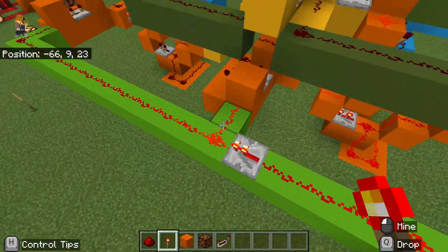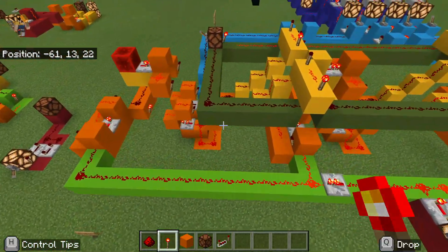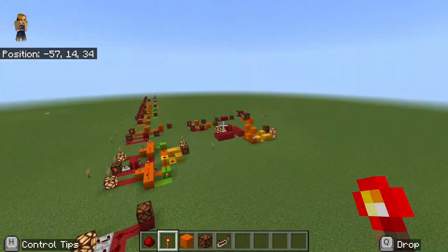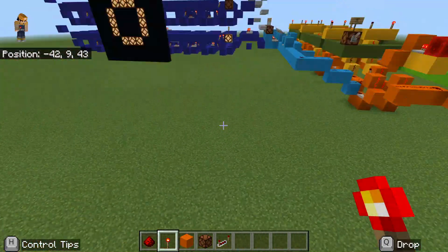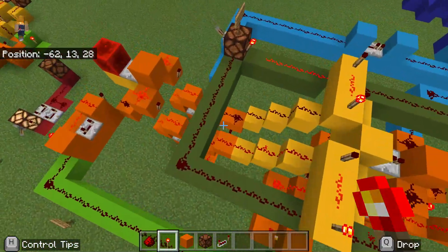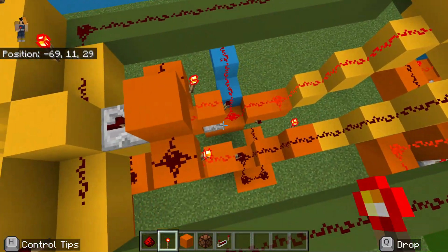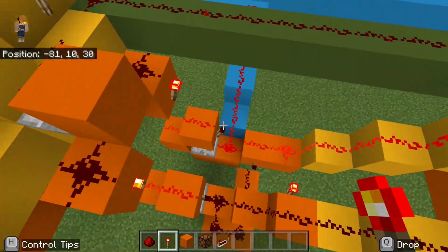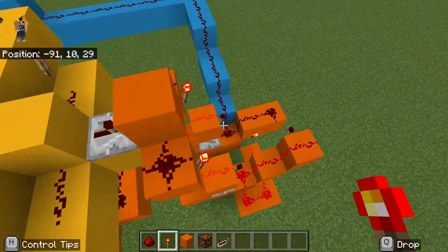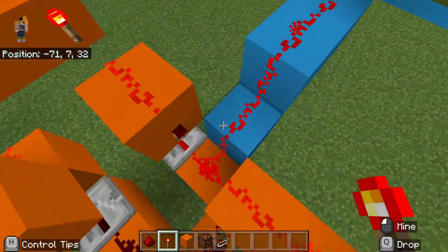So how that works is we have a clock here controlling everything. That's why I was showing you this 3-wide design here. I just copied it 4 times. So we have one JK flip-flop here, feeding into another JK flip-flop here, into another, and into another here.